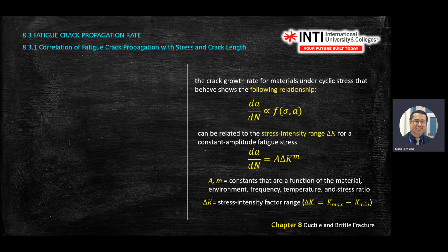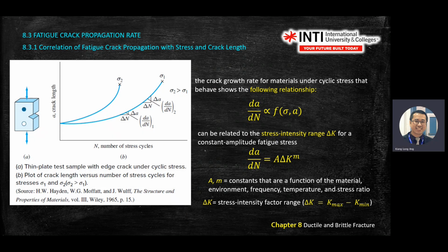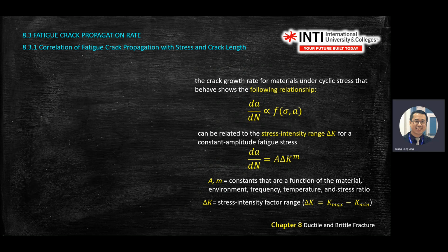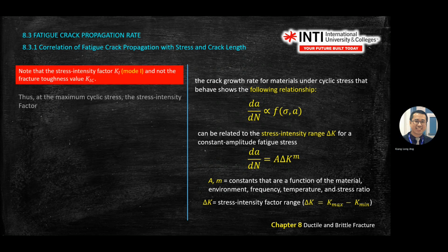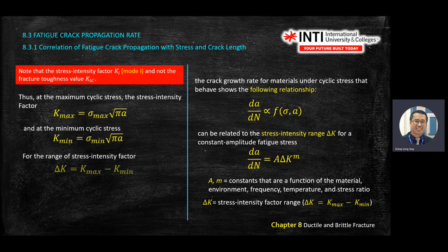Okay, because for this one there's nothing much we can ask you actually. It's quite direct. You pull and then you read from the graph. The rest you read. There's a calculation to calculate what is the stress intensity factor for maximum, minimum, and then how to calculate the delta K.